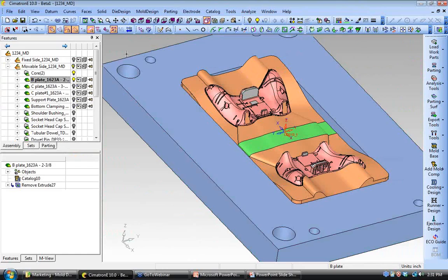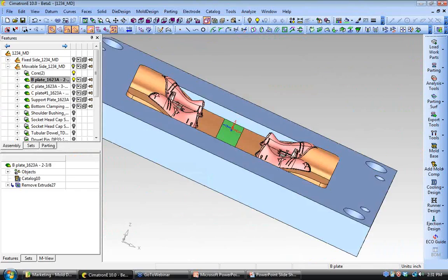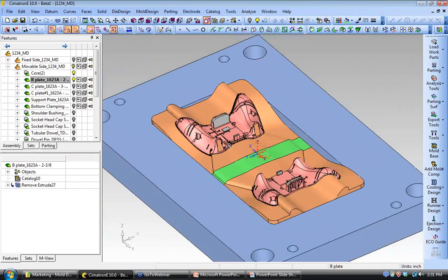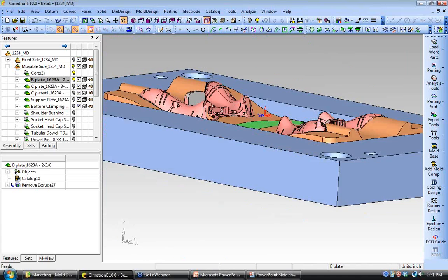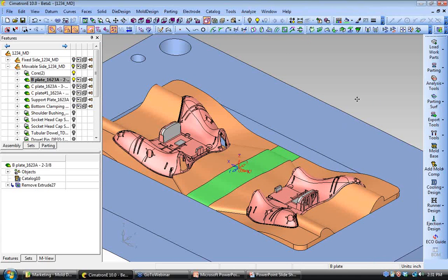Okay. Now, one of those specific mold functions that I mentioned was for cold runner designs. Runners are created by driving a profile shape along a sketched path. And our design today really doesn't have the need for a long runner, but I can show one to show how the function works.